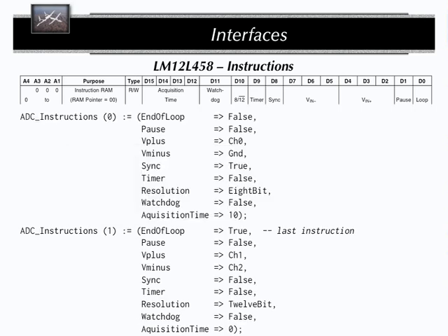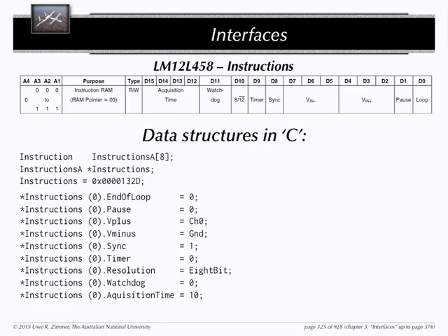If you compare this with here, you actually set the whole record with a single instruction, which, A, enables the compiler to optimize more, do it in one instruction. B, reminds you that you haven't forgotten to set any of the record entries, because if you leave any of the record entries out here, the compiler tells you off: what's the value of that? And for a hardware interface, that's a good reminder to get. Okay, other than that, does it all look okay from the C perspective?